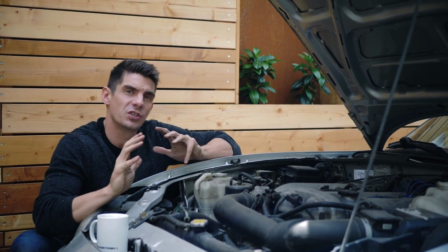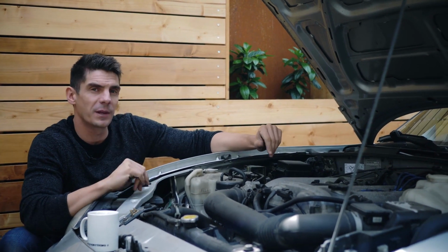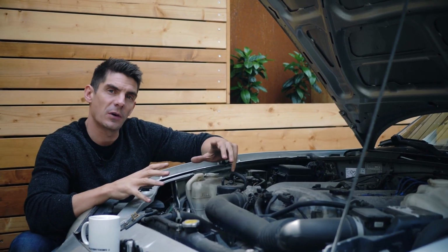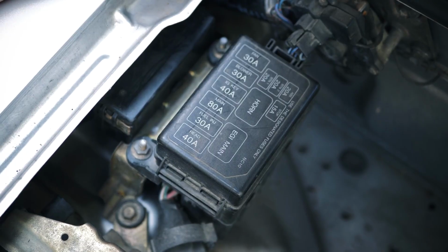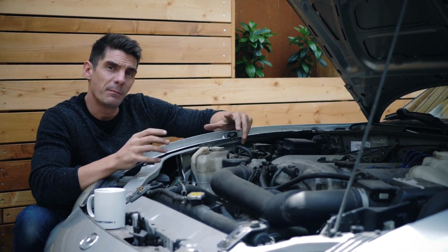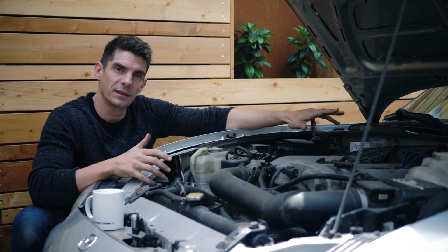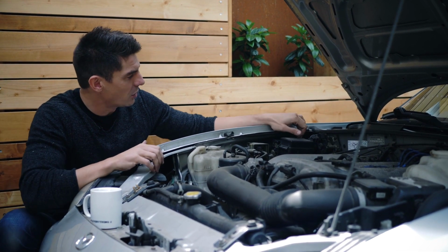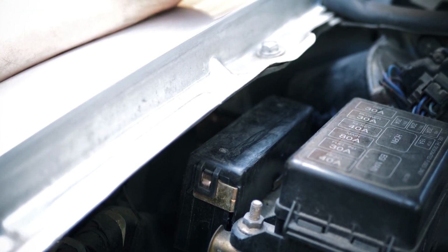Okay, let's say you want to check a relay. The first thing you've got to do is to actually find that relay, and that's probably the hardest part. So the relay could be in the fuse box, and there might be more than one fuse box. There's one here, there's one inside the vehicle here. They could also be in a box of relays, which might be in the engine compartment near the fuse box, might be under the dashboard, in the footwell, somewhere like that. In our case, for the cooling fan, we've got three relays here underneath this plastic cover, so we need to lift that off.